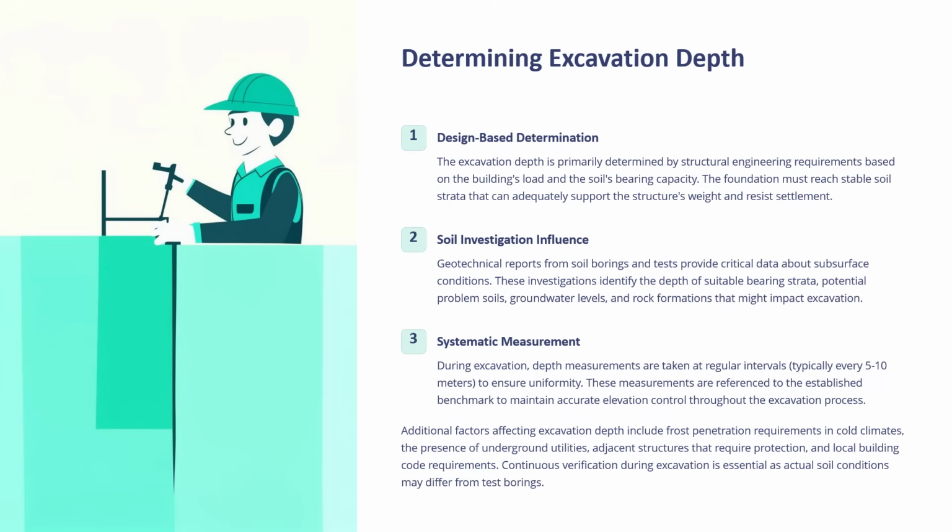Additional factors which may affect the excavation depth include frost penetration requirements in cold climates, presence of underground utilities, adjacent structures that require protection, and local building code requirements. Continuous verification during excavation is essential as actual soil conditions may differ from the test boreholes.